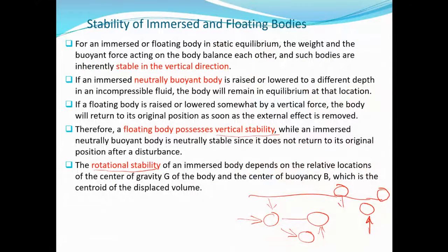This one also, push it down or up. What about the rotational stability of an immersed body? It depends on the relative locations of the center of gravity, G, and the center of buoyancy, B, which is the centroid of the displaced volume.